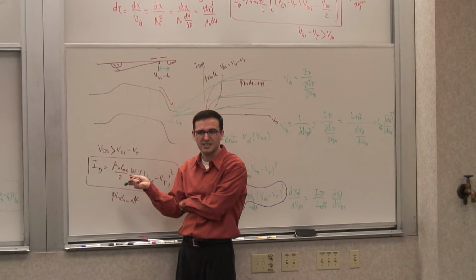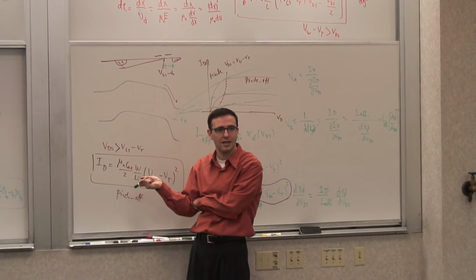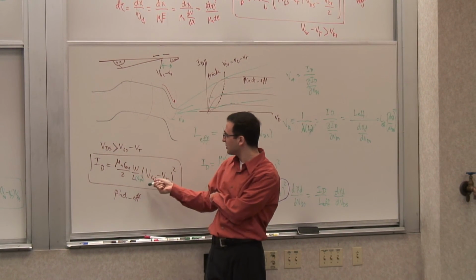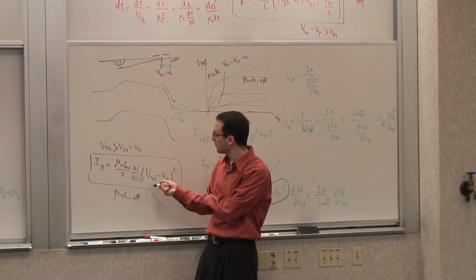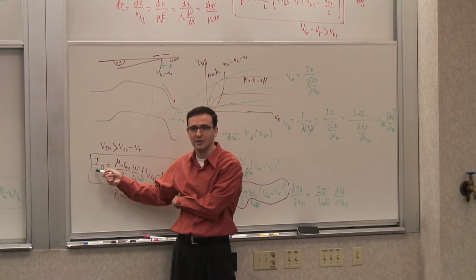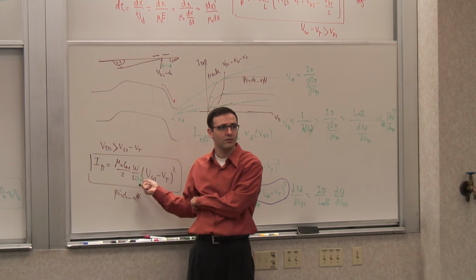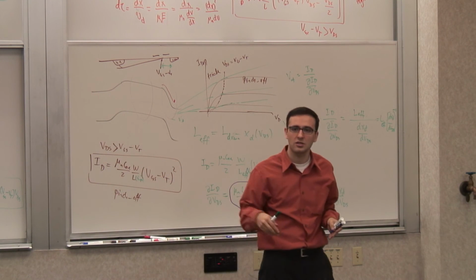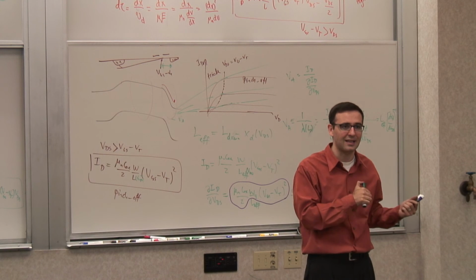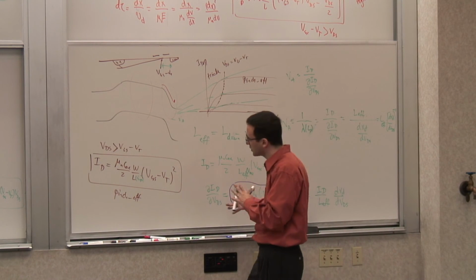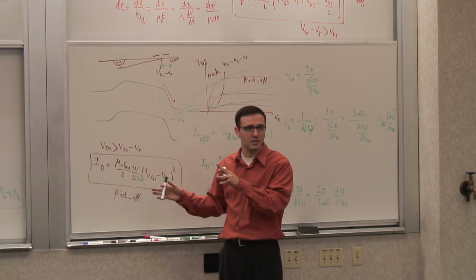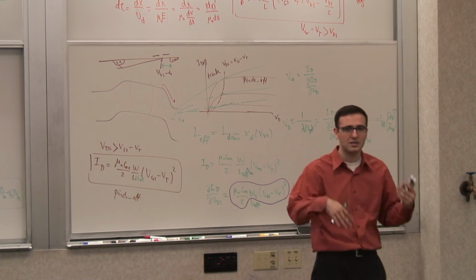In other words, my transconductance. We'll calculate that in a second, but it affects me because if I make my L very large, I may get a very puny amount of current for a given change. So I can't induce a large change in the current. Basically, my gain is affected by that. And we'll do a calculation later which shows the optimum for a given transistor, taking both of these effects into account.